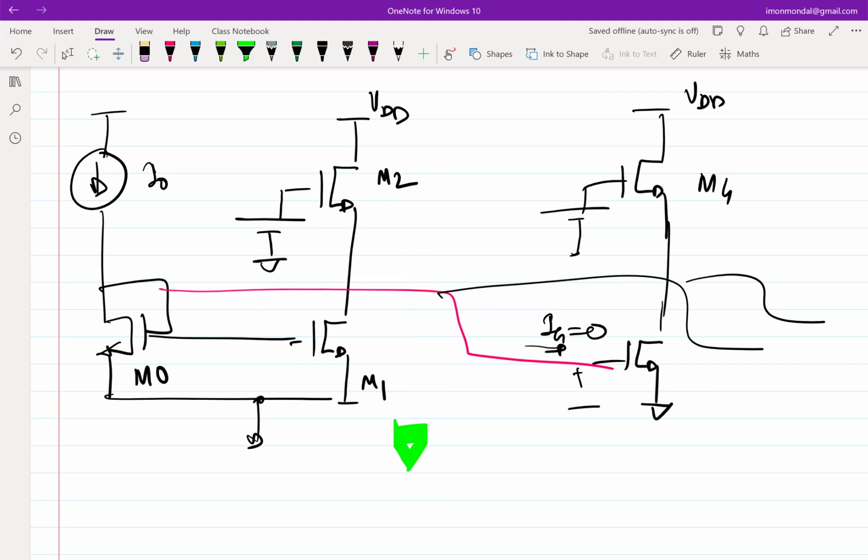Okay. So if you are convinced that this is going to work, the next thing to see is, the moment you connect all these things with real transistors, you have to be bothered about biasing points, right? Ideal current sources, ideal voltage sources, you don't have to worry about biasing. But in this case, you probably will have to worry about biasing. So how do we ensure? So firstly, when we say biasing, we have to ensure that the transistor remains in saturation.